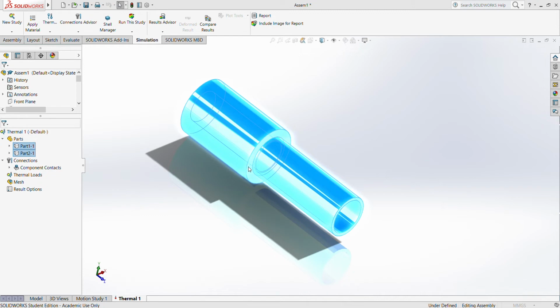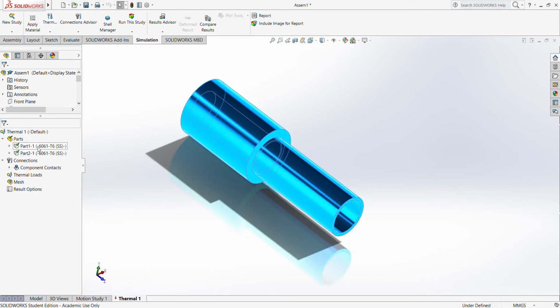Another word for it is automotive aluminum, and we use this for all our spacecraft. This is kind of the main one. There are other alloys if you want larger strength, but 6061 T6 is a good one. So you click that, hit apply, and close. Now you can see it gave you a little check that you selected a material.